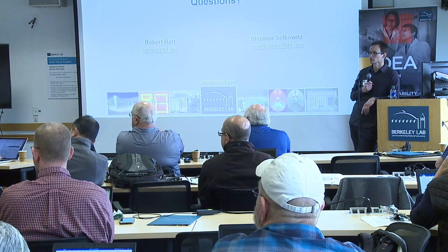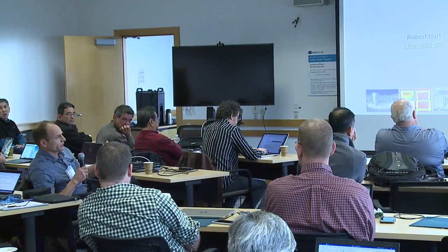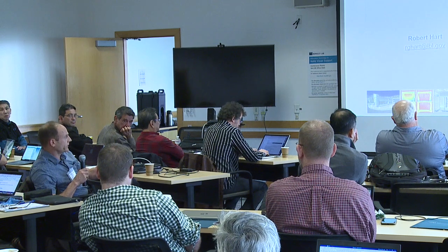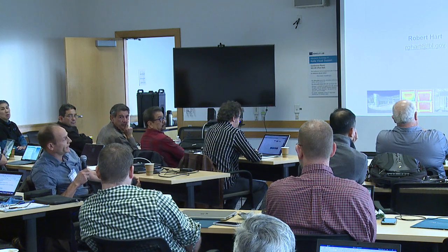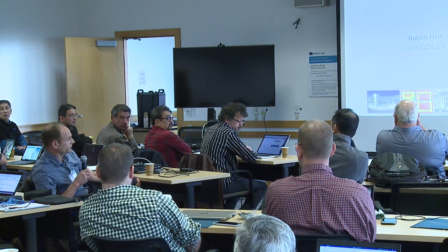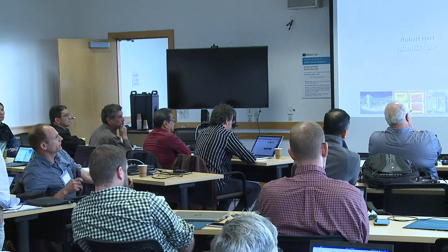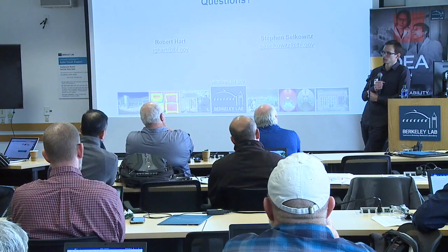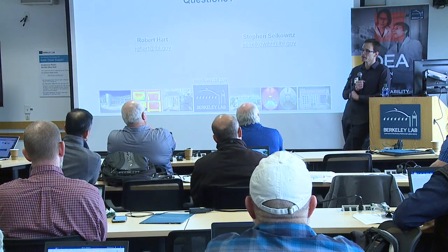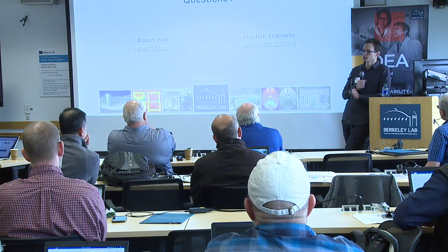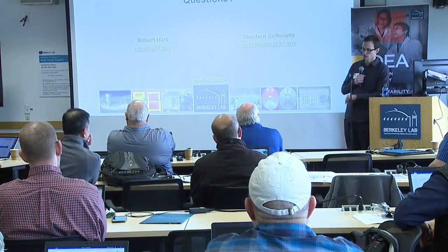So I had a question on longevity or life cycle of glass. You've got this thin layer of glass inside. I think a lot of us have experience with double pane windows. After a while, they lose their gas and get foggy, and you throw them out. But real old glass has a nice sag to it. What is the sag of that thin layer? Yeah, so the sagging part, like leaded glass, that doesn't exist anymore. Float glass doesn't do that. I mean, it does. It's still technically a fluid, but it would be hundreds and hundreds of years before you would see something like you see in old leaded glass windows. So that's not an issue.